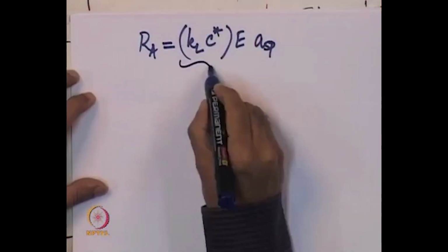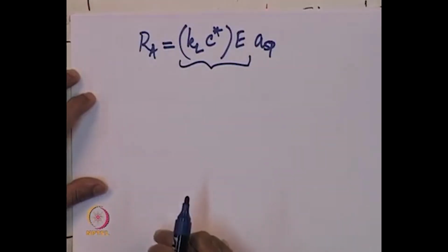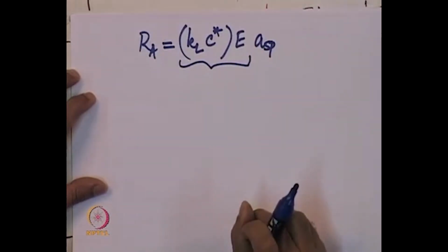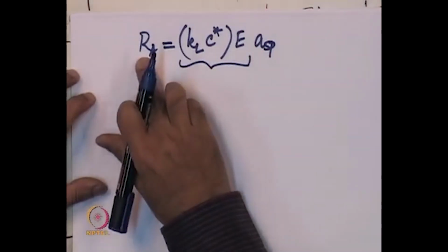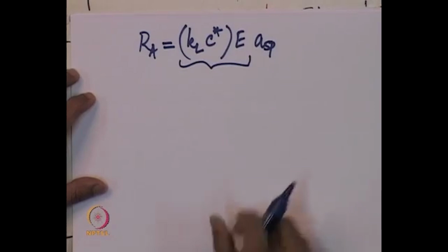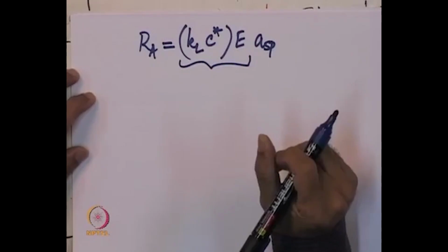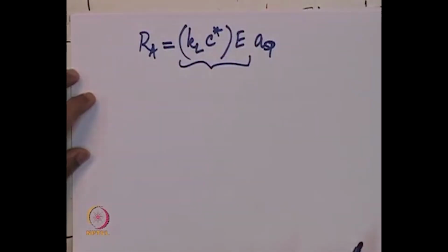And in this example, we have encountered the interfacial area per unit volume of packed space. So, basically it does not make a difference to your calculation of the flux at all, because that is given by this expression here. Depending on what units you want the rate to be in, you have to multiply this by the appropriate type of interfacial area per unit volume. So, here the rate is required in moles per unit volume of packed space per second. So, we use the interfacial area as square meters per meter cubed of packed space. So, that is a matter that is fairly trivial and does not need to engage our attention any further.